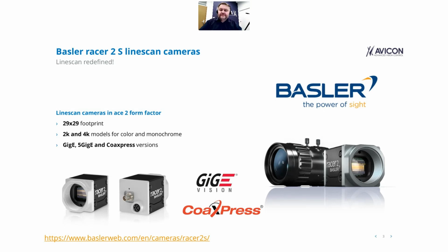And also interfaces are quite important. We have three options available. This is the GigE, the very classical, standard, old school way of doing machine vision, very stable, long cables, very nice. Also, we have a faster 5GigE version, which differs in the bandwidth of the data. And for exceptionally fast processes, where we have to go tens or even hundreds of kilohertz for extremely fast moving objects or extremely high resolutions, we have an option of CoaXPress.